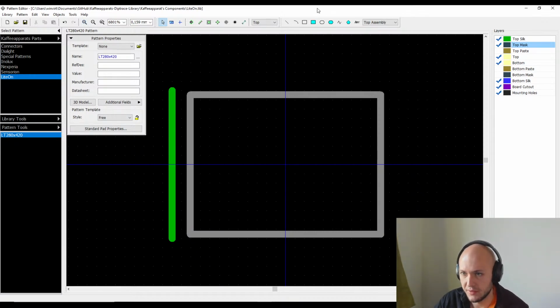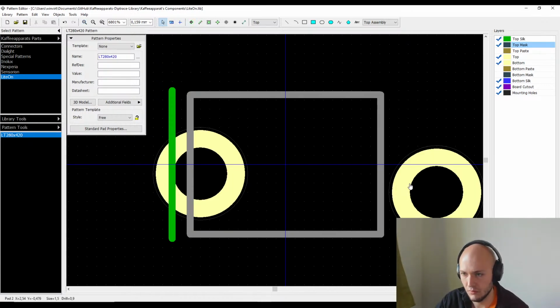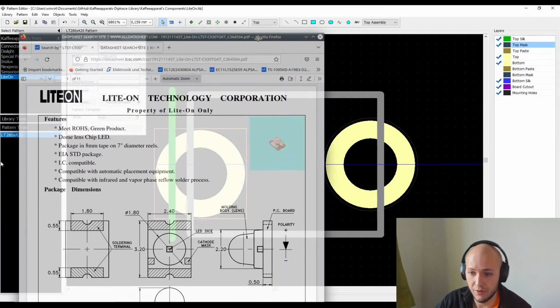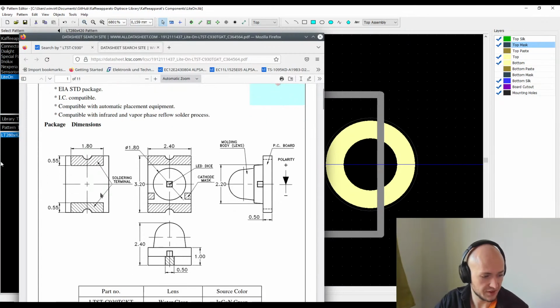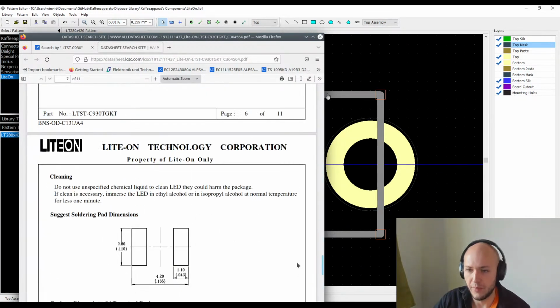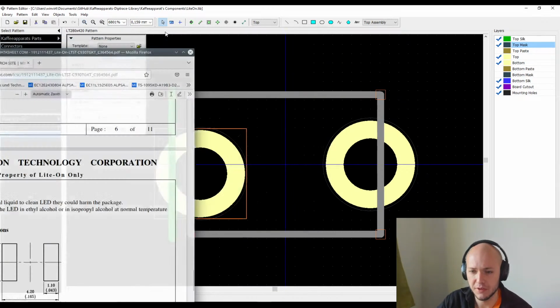And add the pads. We add the pads above here, 1 and 2. So the pads will have certain dimensions, and if we compare those, first of all we worked with these dimensions, and next we would work with the pads themselves. So we will have 2 pads with the dimensions of 2.80 times 1.10 millimeters, and we'll put them apart 1.20 millimeters.